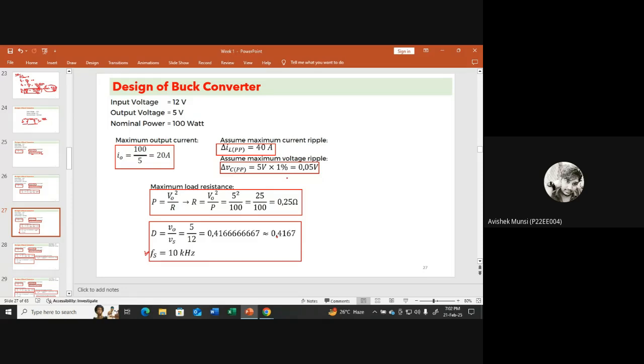We have to consider these things and solve, and then finally we can design our circuit in a simulation platform like SPICE, like LTspice, after which you can apply some parasitics, and then we can move into the circuit design in hardware. Then you can validate it and design the PCB of that, and see that it's working.